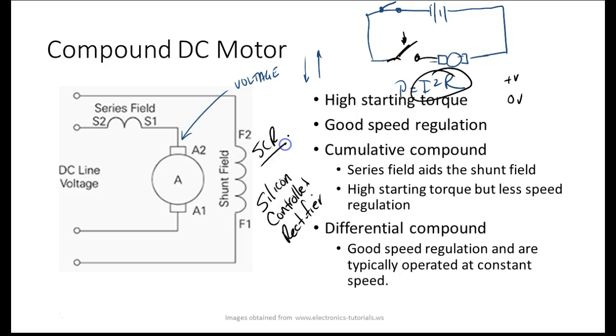Called SCRs. Very popular. The problem with SCRs is that once you turn them on, the only way you can turn them off is to take the current away. So they work real great on AC because AC reverses polarity 120 times a second, right? So you turn them on, and then they'll conduct the rest of the cycle. So I might be putting this into my pulsating DC,